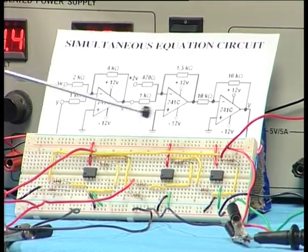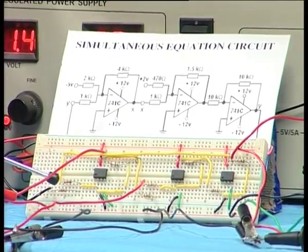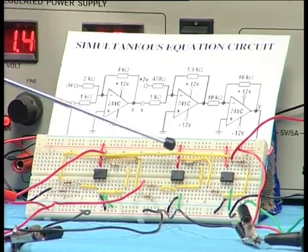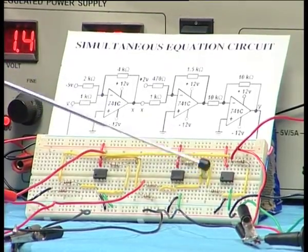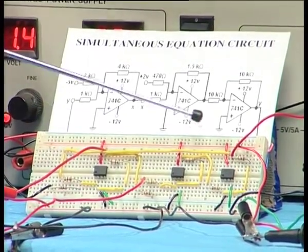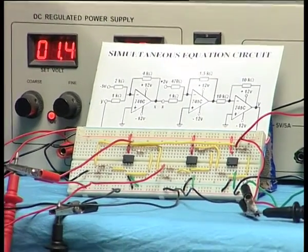So this is the actual circuit wired with the 3 op amps as seen here. This is the first op amp that you have here, you have got the 1k and the 2k and the feedback resistor, all those things, and this is the second op amp here, and you have got the 470 ohms and the 1k and the feedback resistor 1.5k, and the last one is 10k with the feedback resistor 10k, an inverter, and the output of that is all the way brought and given at the input corresponding to y. So this is precisely the same circuit which I have wired, and I wanted to measure the voltage here.